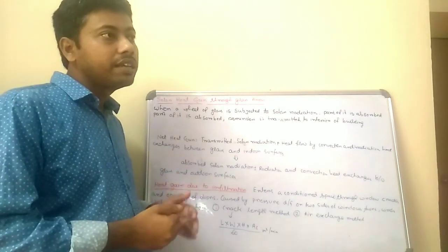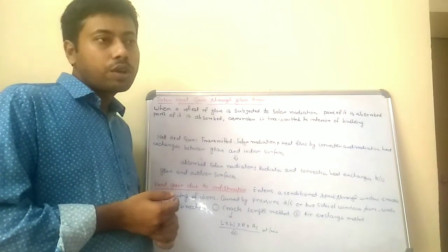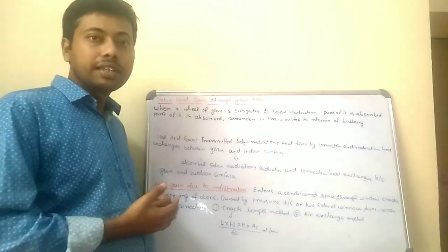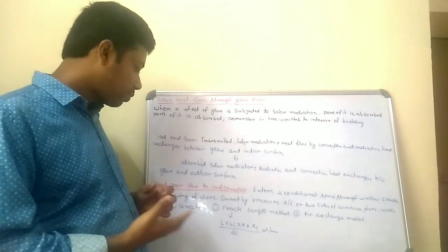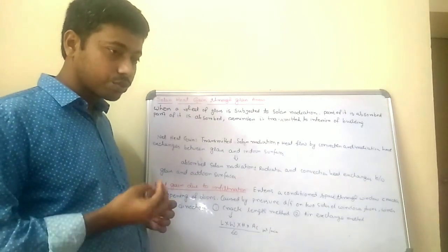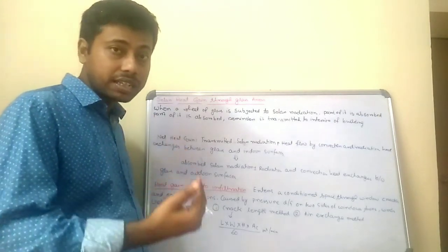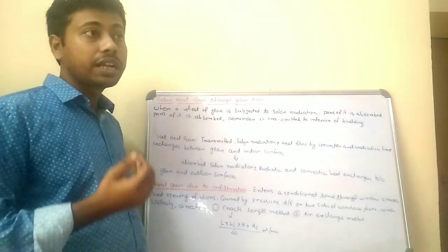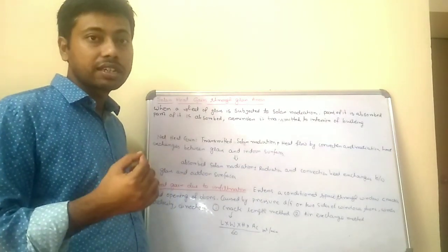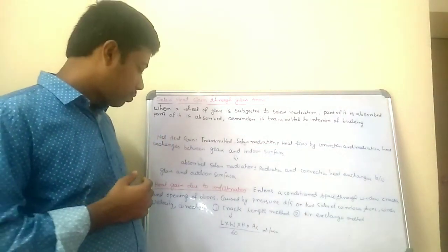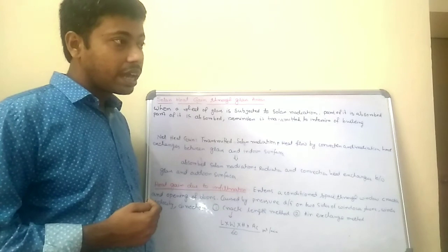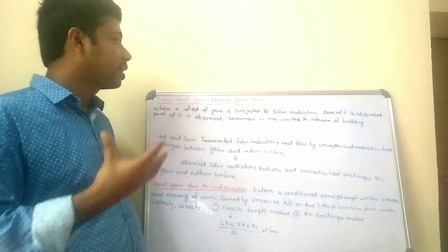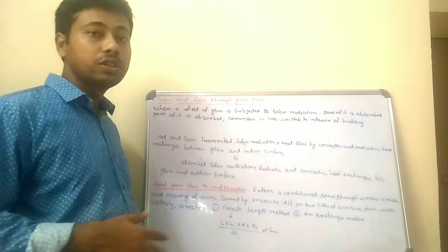So this air can increase the temperature of the room where air conditioning is working. So there is some extra effort by the air conditioner, and there is some power loss. That's why when you calculate the cooling load estimation, we have to consider whether there is any gap, any crack, or any repetitive opening of doors. As much as we can consider all those things, we can get actual results. So this is the heat gain due to infiltration, and there are other variables that can impact the cooling load estimation.